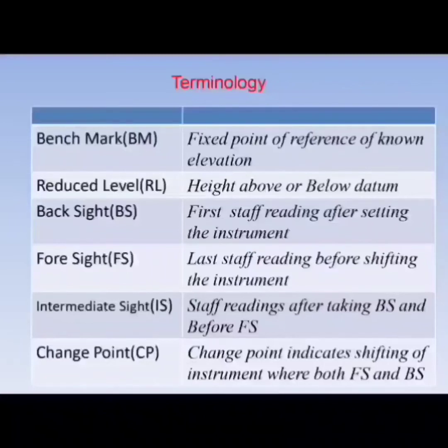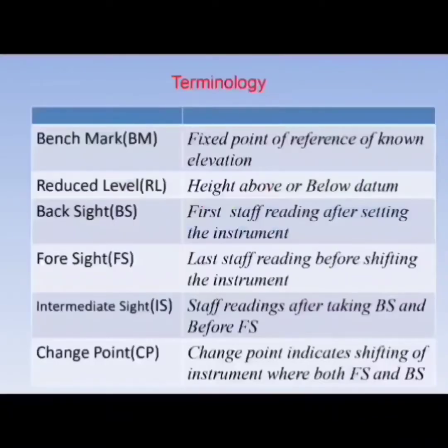Benchmark is a fixed point of reference of known elevation. Reduced level is a height above or below the datum. Backsight is the first staff reading after setting up the instrument. Foresight is the last staff reading before shifting the instrument.